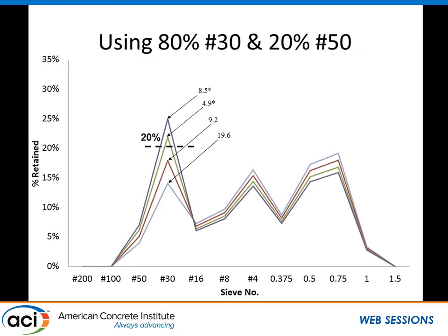Everything over here is constant. You say, well, why does it move up and down? Because I'm changing the volume of my sand. If I take out some sand, I have to add in coarse aggregate to make it go up to 100%. Okay? And as we can see, the curves are going to look the same over and over again. You're going to see high to a good point and then a high point again. And we had some surface finishing issues right here.